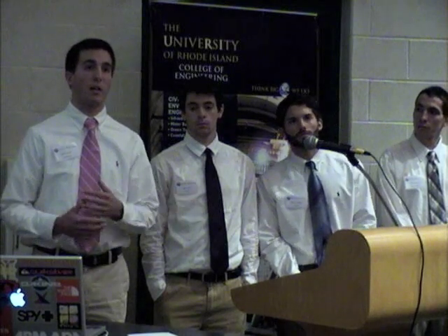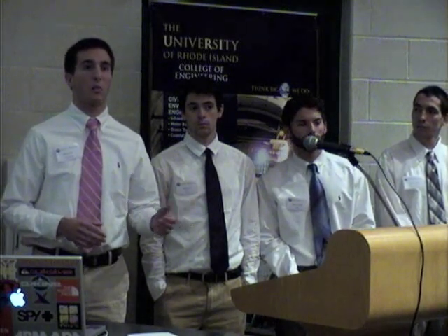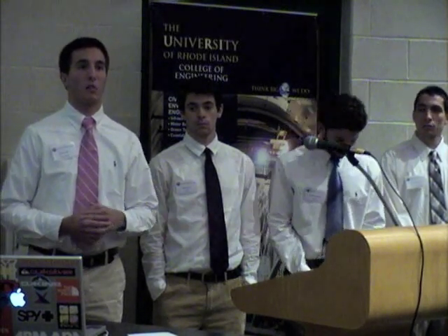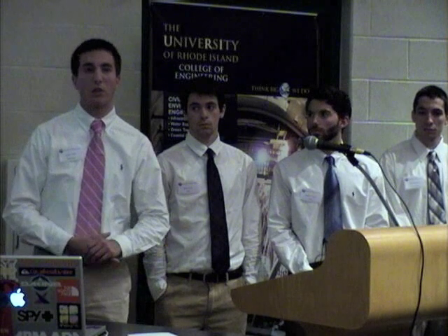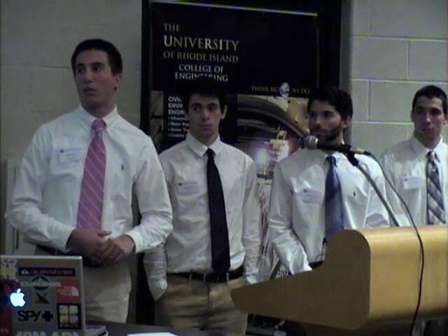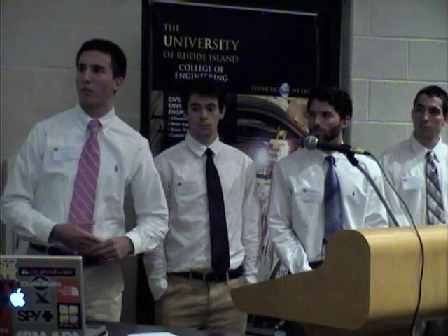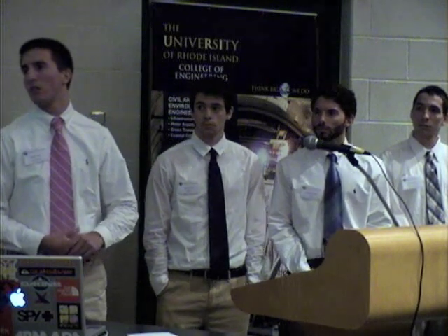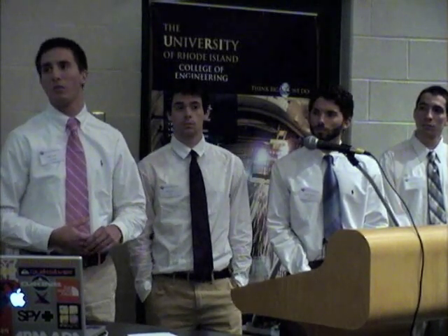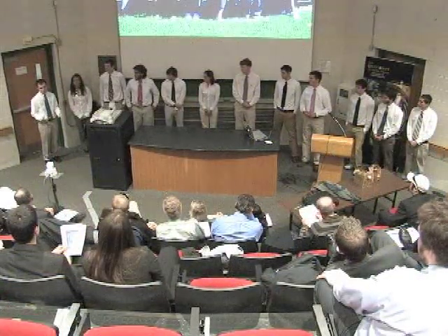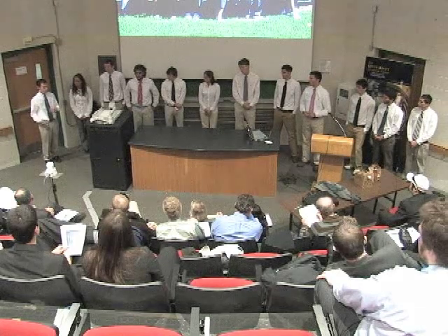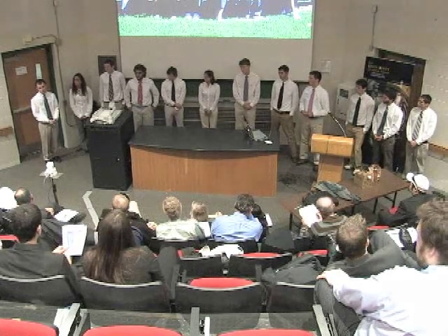We're going to go back and make sure everything is the way we want it, and go back into designing everything, whether it's beams or layers of materials. I know Chris was the main designer for the road designs, and as far as the road designs and thickness, they went based on a standard design for new construction. Because the material underneath the road is questionable, that's why we proposed a 12-inch processed gravel that we're going to bring in as sub-base for the road.